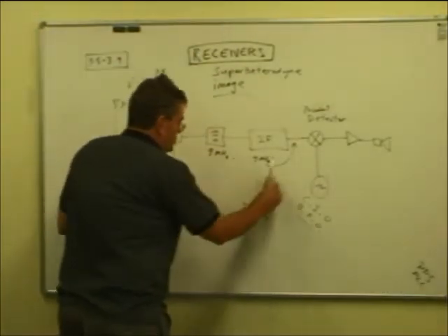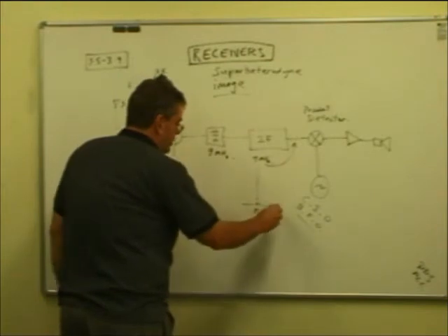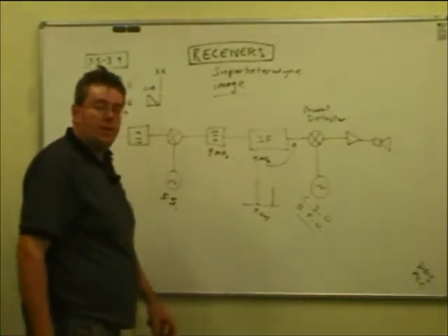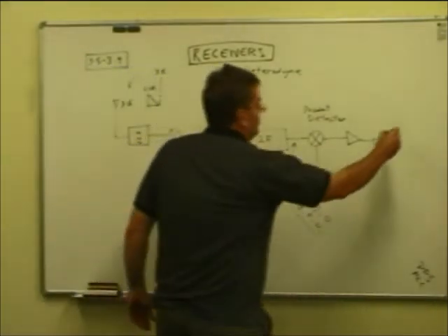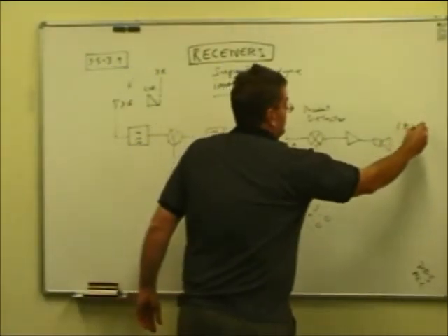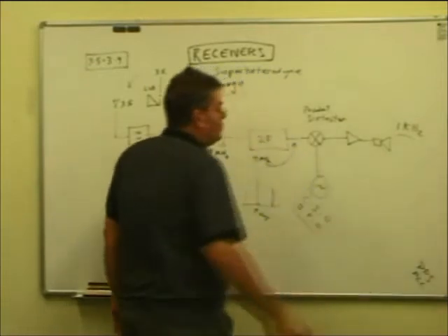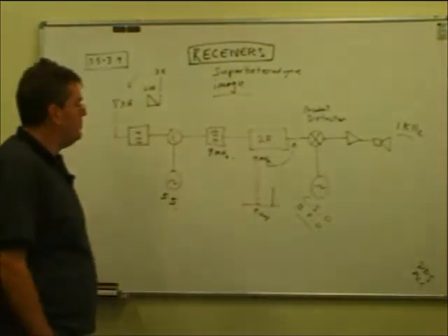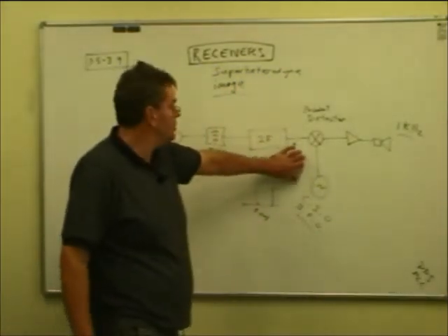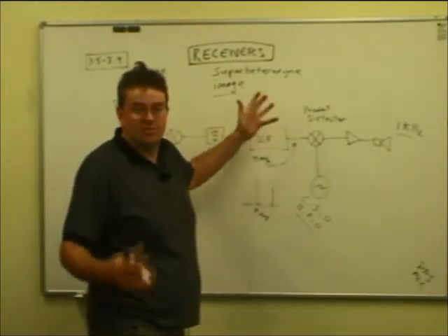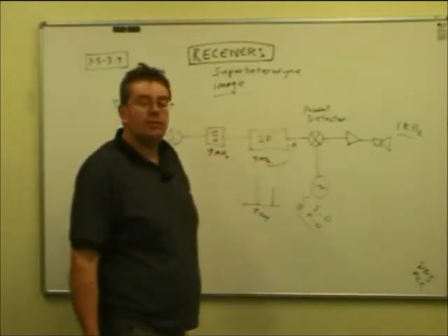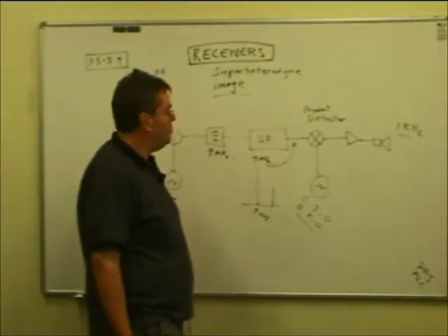So what we have to do now is we want to get that 9.001 megahertz tone back down to 1 kilohertz, which is what it originally sounded like when it went into the microphone. And here we use that F1 plus F2, F1 minus F2 process that mixers do. The straight AM detector is just called a detector, but a detector for detecting single sideband is called a product detector.